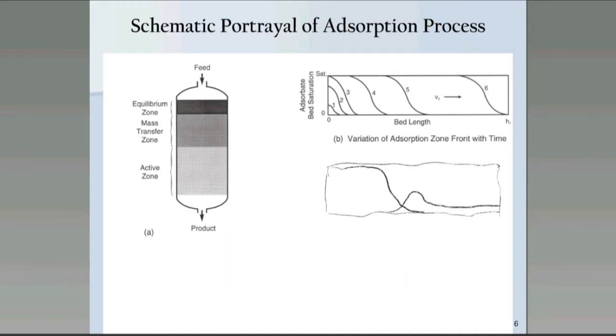Wherever the regeneration gas goes, you need to ask yourself the question of, will the downstream process be able to tolerate that peak in H2S? If you cannot, you may have to put in a small amine unit on the spent regeneration gas. In addition, you can see that the water will peak during the regeneration because we, again, are using a smaller flow rate of regeneration gas compared to the feed flow rate. So the question you also need to ask is, will the water spike throw you off specification if, for instance, you plan to blend in the spent regen gas with residue gas that is leaving a demethanizer? If it does throw you off spec, you may have to put in a small TEG unit in the spent regen gas line.